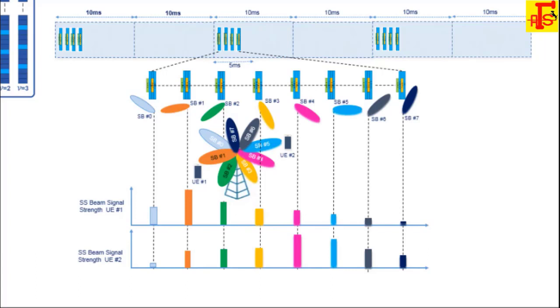So that it decodes the PBCH MIB content information such as SFN, SSB index, raster offset, DL numerology, RMSI configuration, DMRS location, and cell barring related information. So all these things are decoded after reading the DMRS signals and PCI information.